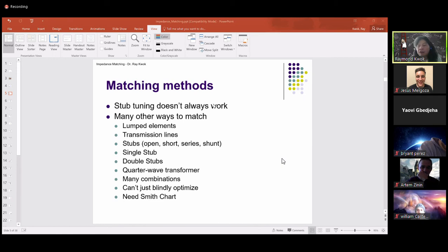It depends on the surroundings. Remember, if the circuit is too close to the wall, the electric field might connect to the wall instead of to the bottom ground. So you change the electric field or magnetic field patterns. That changes your inductance or capacitance, and so that will change your impedance, and so your impedance becomes unknown. That's why a lot of times when you put the circuits together, if you don't consider every little detail, it will not work, right?